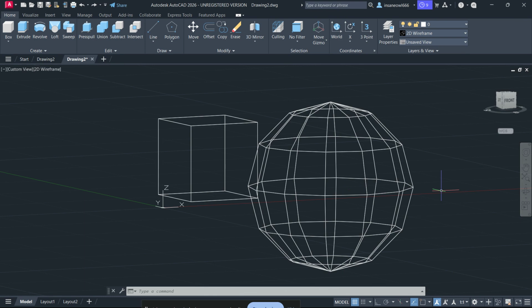So, to quickly recap, if AutoCAD error code 97008 appears, first try the micromove, then clean the body, then check validity, then simplify the geometry, scale up if needed, and finally use incremental union to isolate the bad object. In most cases, one of these methods will solve the issue without needing major redesign work. The key is to remember that this is usually a geometry problem, not a random AutoCAD glitch.